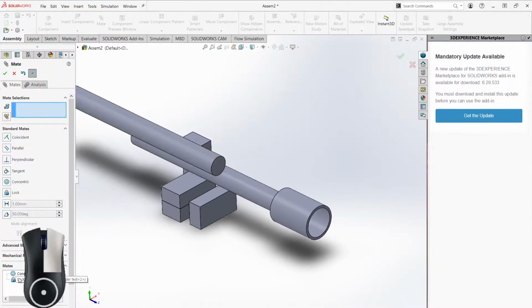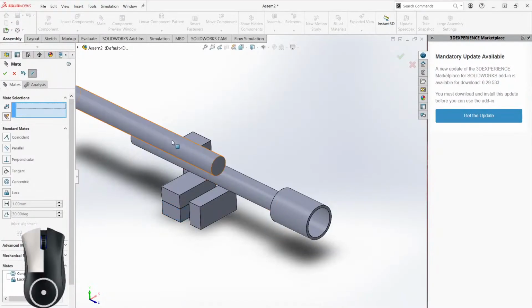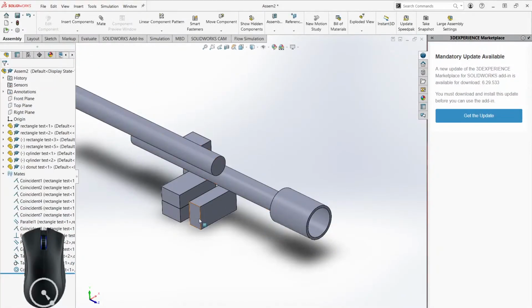Let's delete that one that I just did, but if I had done this one and this one, which doesn't move, right? Now you can see this doesn't move anymore. Can't move this around. All right, but locking typically isn't that good because it stops any movement in your assembly that you might want to move later, even if you don't want it to move right now.